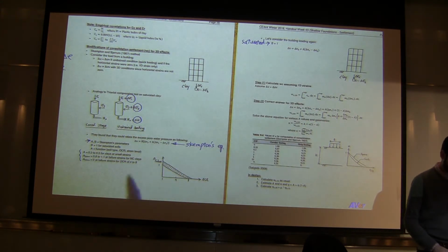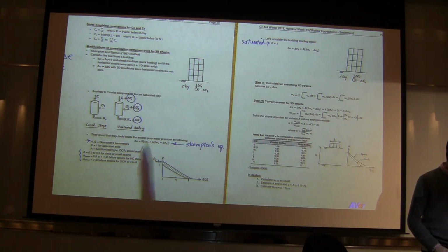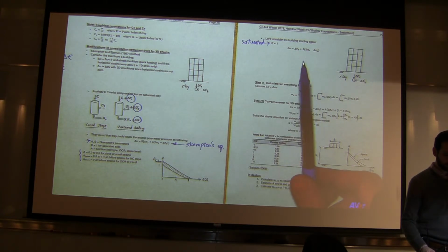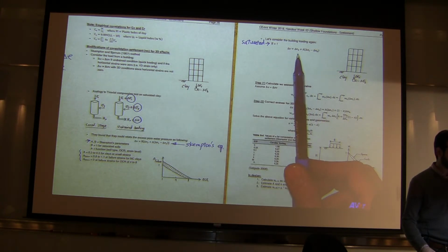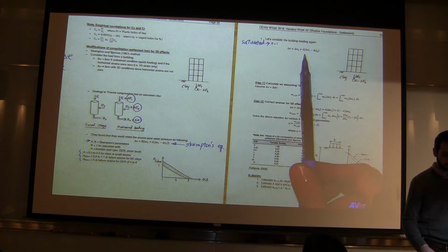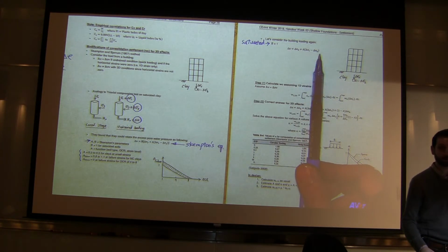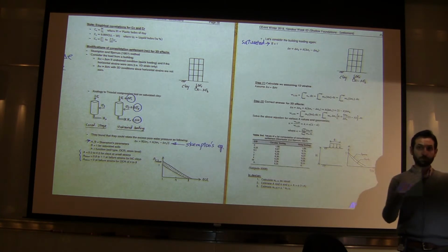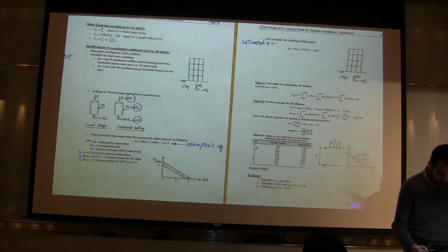If B is 1, in a triaxial test we have delta sigma 3 plus A times (delta sigma 1 minus delta sigma 3). In the real world, in this building example, it becomes delta sigma H, the horizontal stress, plus A times (delta sigma V minus delta sigma H). Okay? So it's the same equation, except now I'm writing in terms of horizontal and vertical stresses.